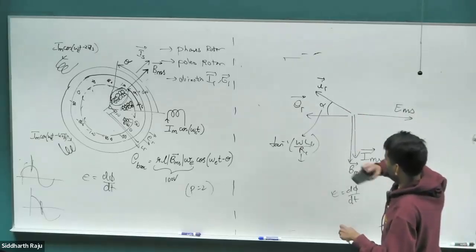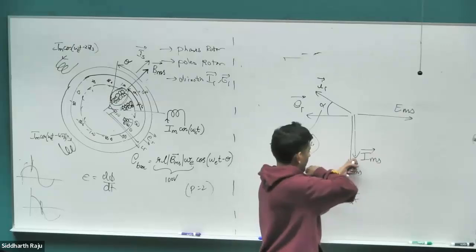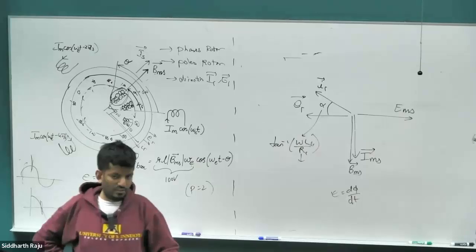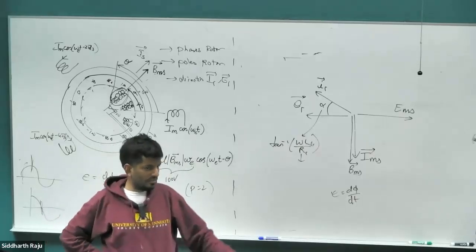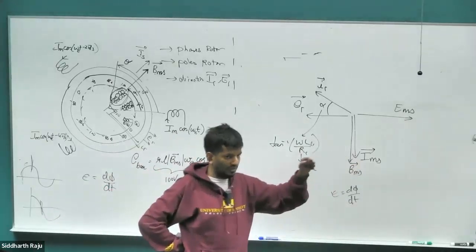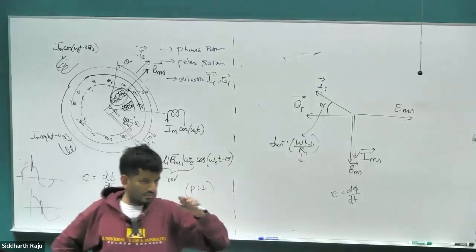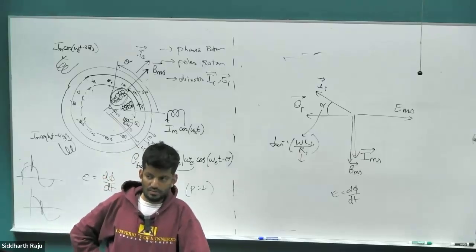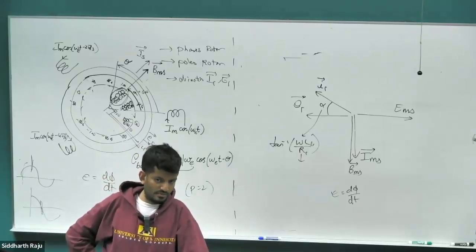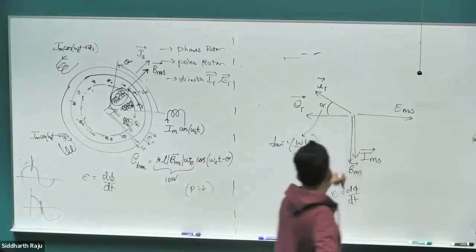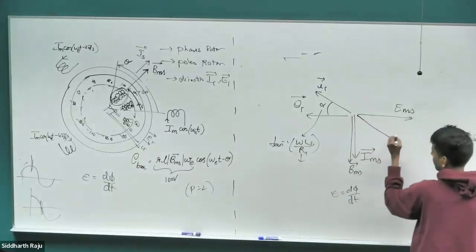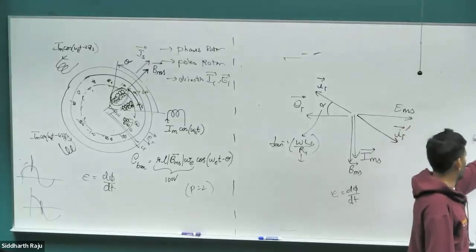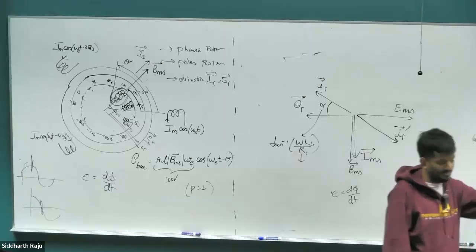So this is going to be a rotor current. This is going to be the stator current that's establishing the magnetic field. Is that all the stator current is going to be? Is this the only current that's being drawn from the stator power supply for the induction motor that we have? Or is there any other current? I2 prime. In our case, rotor current prime. Because again, going back to this diagram, you had some magnetizing current IM.